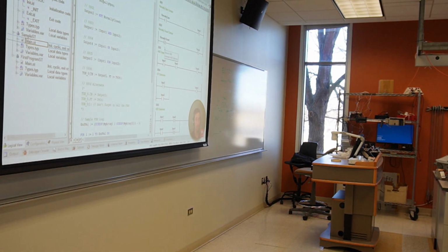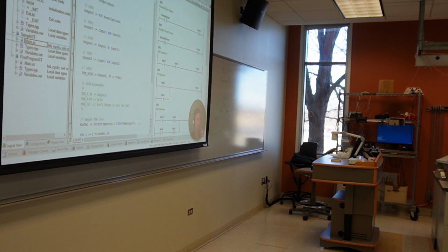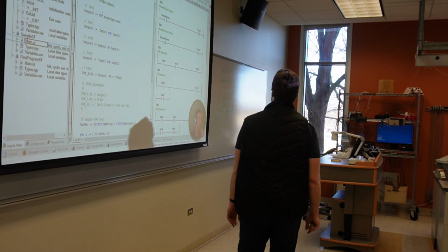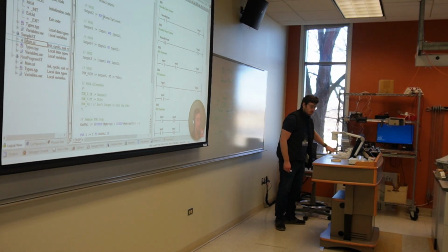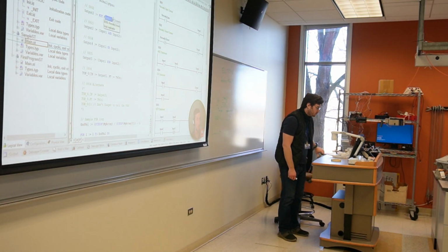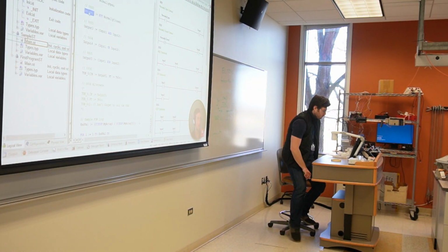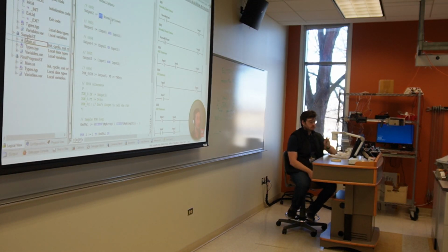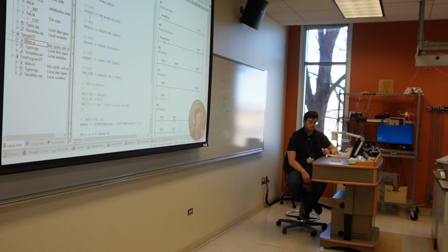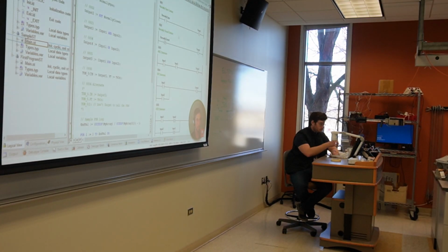Used to programming ladders. Well, how do I do a normally closed contact? It's really simple. Actually, all you need to do is have this NOT here. So you can think of the NOT as a normally closed. Essentially, if normally closed is true, then output 2 will be false, and vice versa. So that NOT is going to invert whatever normally closed is. That's how we can use a Boolean operator to simplify what we're going to do inside of ladder.